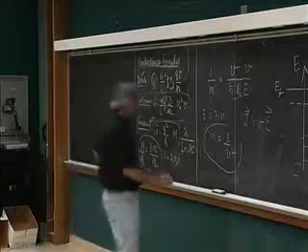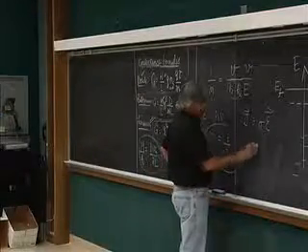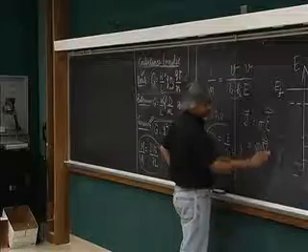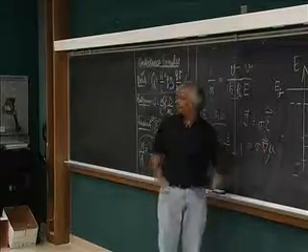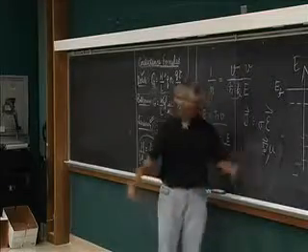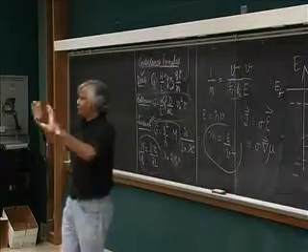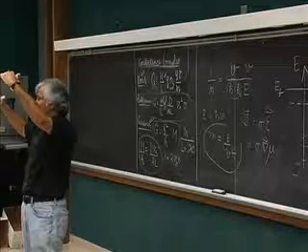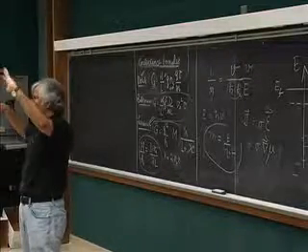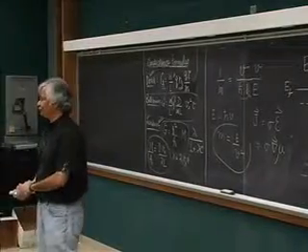Current is really driven by sigma grad mu. What really matters is the gradient in the electrochemical potential. So it will flow because up here the electrochemical potential is high and low somewhere else. That's really what is driving current. It's not the electric field setup, really.